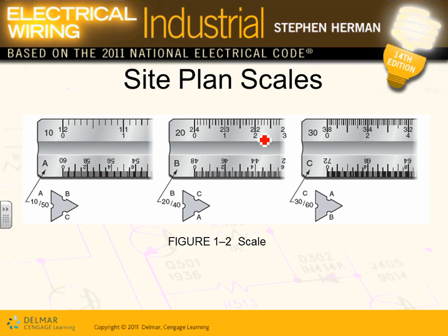What is an invert? The bottom of the lower conduit. It's called invert. Scales. When we use scales, guys, there are two scales that we use: an engineering scale and an architectural scale. This one is called the engineering scale. It goes by 10, 50, 60, and so on. The architectural scale goes by 1/4 and 1/8 and 1/16. That's what we were doing when we were scaling yesterday, the architectural scale.